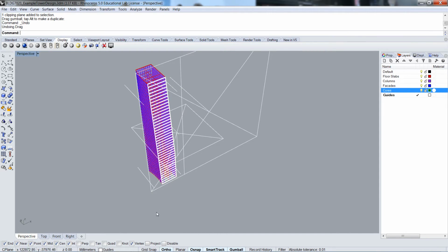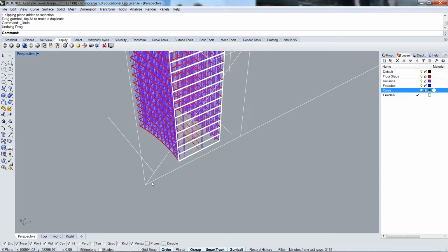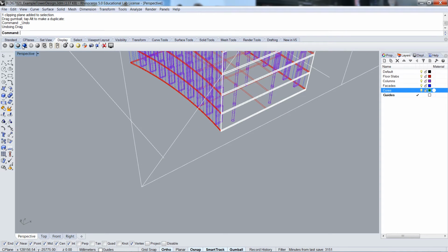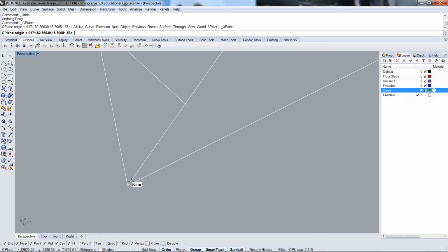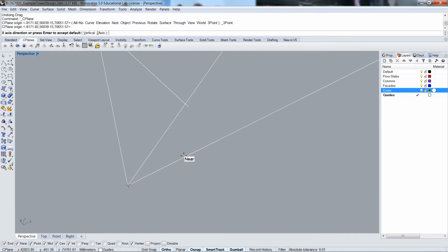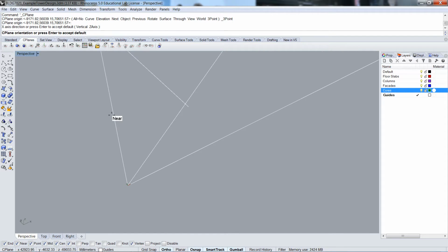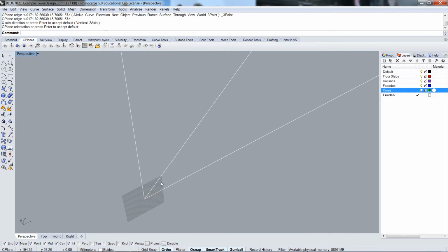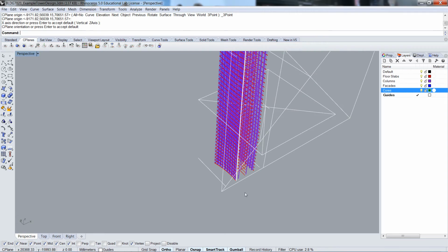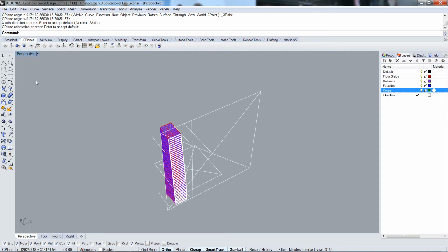so that we can save off this information. Now if we head down here, I'm going back to my construction plane, 3 points. There's my origin. I can use my clipping plane as a snapper. My first point, and then I'm going to clip to the top, and there you can see it's lining up with my clipping plane. Okay, so I'm going to do Make 2D again.